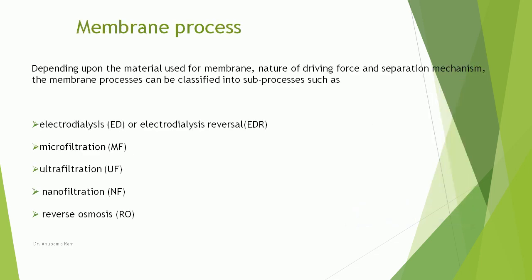Now coming to the next tertiary treatment process, which is the membrane process. Membrane technology can be used to treat a variety of wastes, including sanitary landfill leachate containing both organic and inorganic chemical species, water-soluble oil wastes used in metal fabricating and manufacturing industries, solvent water mixtures, and oil-water mixtures generated during washing operations at metal fabricating facilities.